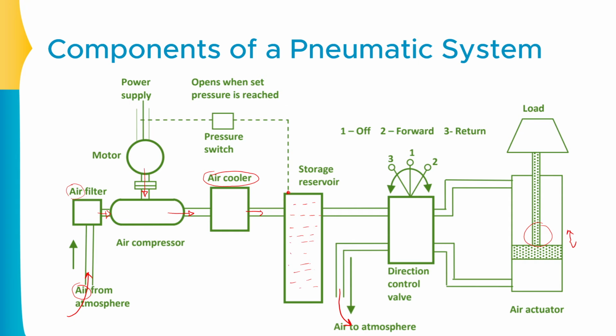If the storage pressure of this container is low, the pressure switch will be kept closed. Due to that, the power supply continues and the motor continues to run.